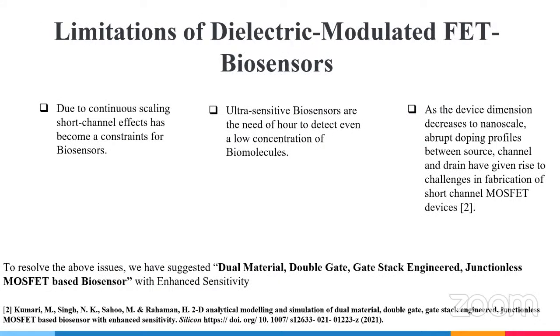As time goes on, there is continuous scaling in the CMOS industry, so there are limitations of the dielectric modulated FET-based biosensor that we have studied. First, due to continuous scaling, short channel effects have become a constraint for biosensors. Second, ultra-sensitive biosensors are needed to detect even a lower concentration of biomolecules.